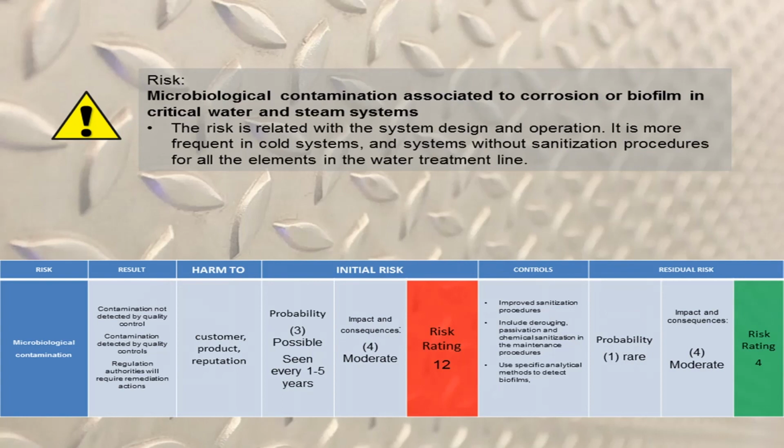The classical culture approaches of water testing, such as pour plates, spread plates, membrane filtration, and the most probable number, do not always detect biofilms. If we control the microbiological quality of water with a method which is not sensitive to biofilms, we have the risk of regular undetected contamination. In other words, sometimes we have positives, others false negatives.